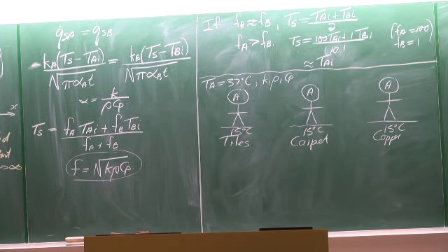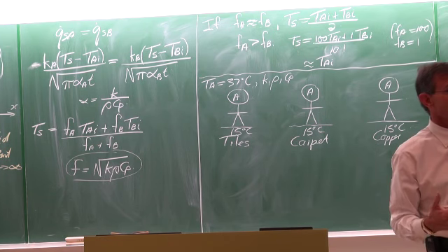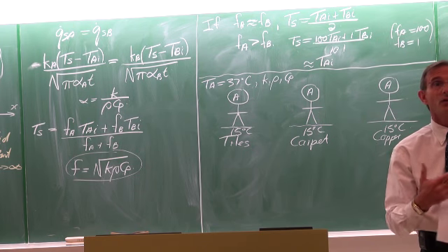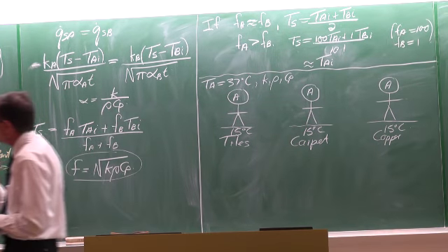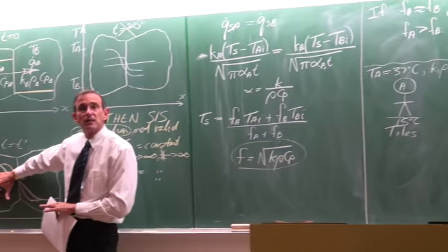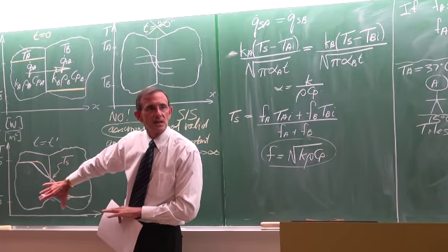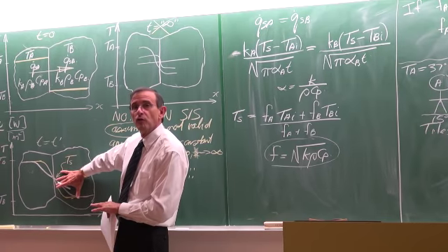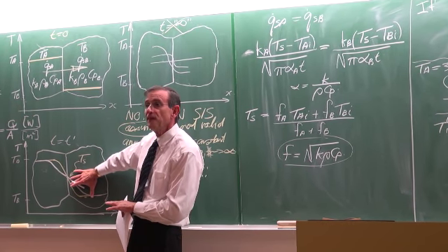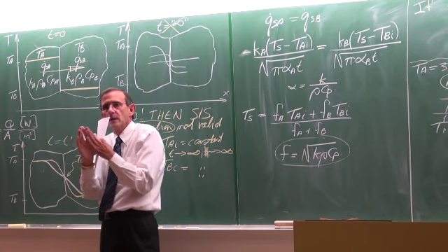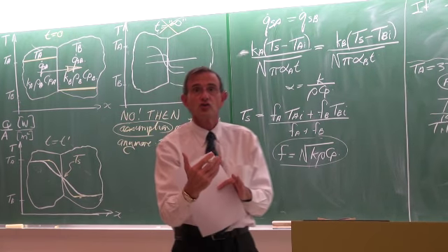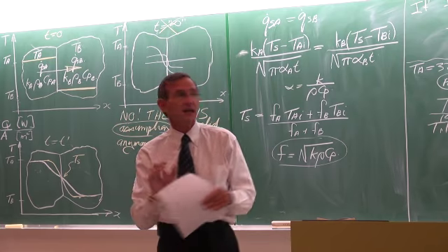Let's look at these three scenarios in terms of the reaction on your body in terms of surface temperature and in terms of how much heat is being transferred. If we look back at these two semi-infinite solids, your body is at 37, and the floor, tiles, carpet, or whatever is at 15, and it's another semi-infinite solid. We want to see close at the surface what happens to the temperature and how much heat is being transferred for these three different cases.